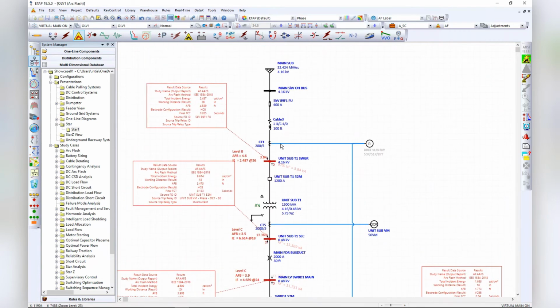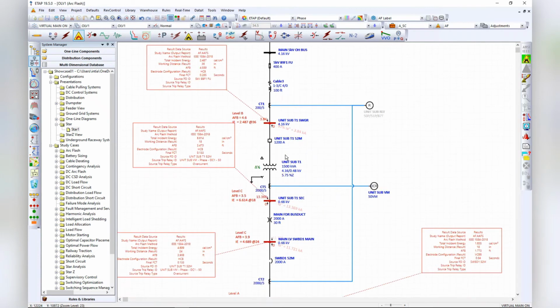Maybe this breaker is upstream in a 5 kV switchgear that feeds the whole plant, or a 15 kV switchgear feeder somewhere upstream. That's not the point now. The point is you need to go and trip on the primary because you need to interrupt the whole energization of the transformer. So that's very popular, virtual main.